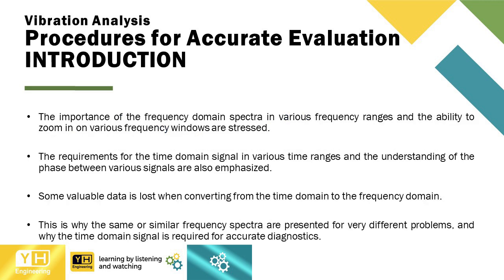The importance of the frequency domain spectra in various frequency ranges and the ability to zoom in on various frequency windows are stressed. The requirements for the time domain signal in various time ranges and the understanding of the phase between various signals are also emphasized. Some valuable data is lost when converting from the time domain to the frequency domain. This is why the same or similar frequency spectra are presented for very different problems, and why the time domain signal is required for accurate diagnostics.